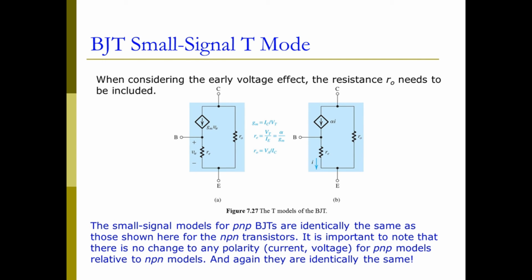But for small signal analysis, as we can see, we model those junctions using a resistance value, so we don't care about the direction. That's why no matter whether PNP or NPN transistors, their small signal analysis will be exactly the same. Okay, I think that concludes this part.